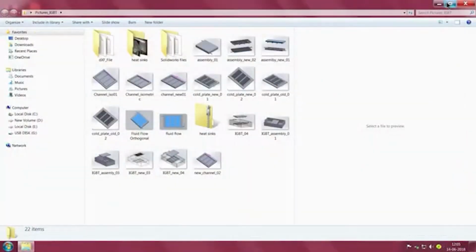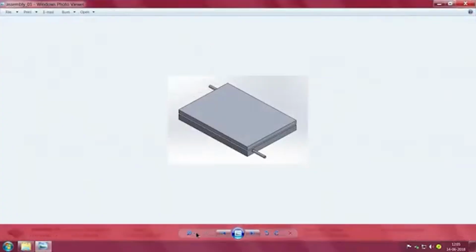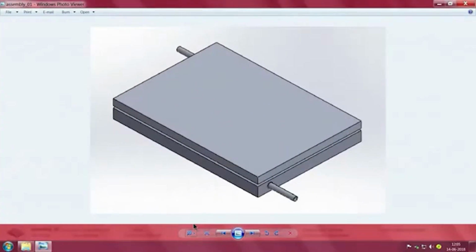So, I will stop here. Enough of it. Now, a small portion inside this is this water cooled cold plate. On the top surface we mount the power devices, and the bottom surface is part of the casting, so that we can make the maximum use of it. And what you see here is channels have been made for the cooling of it.